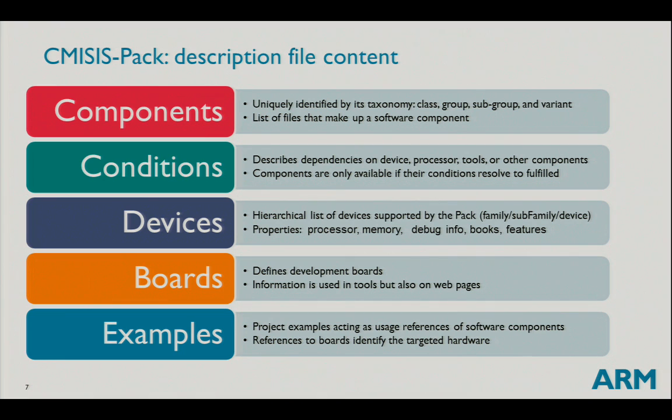Components can depend on hardware, so they are supposed to run, for instance, on the STM platform, and they can depend on each other. The conditions are intended to describe those two kinds of dependencies, hardware and software. A pack can also contain device descriptions in a hierarchical way, from family and subfamily to the variant.